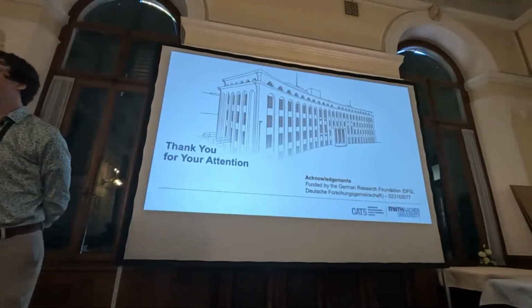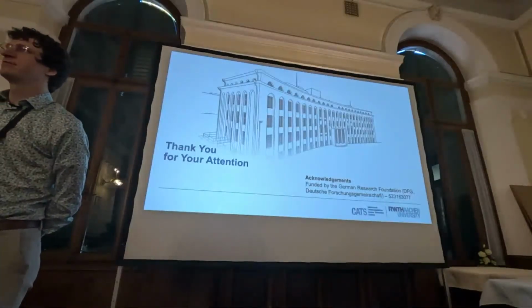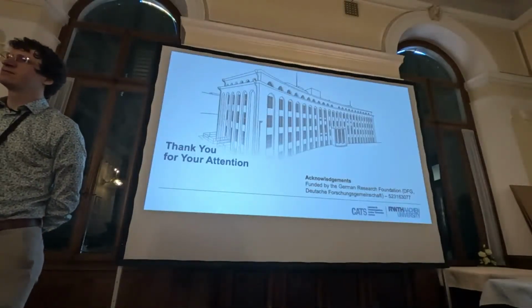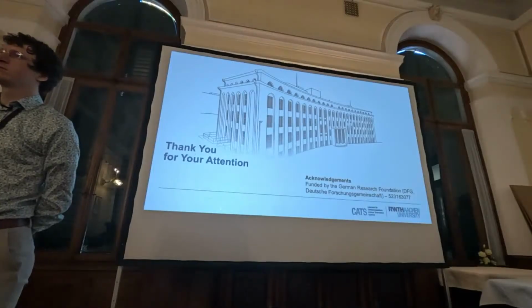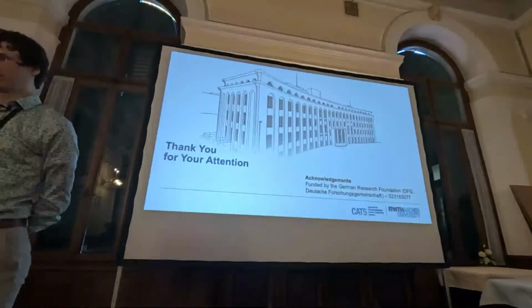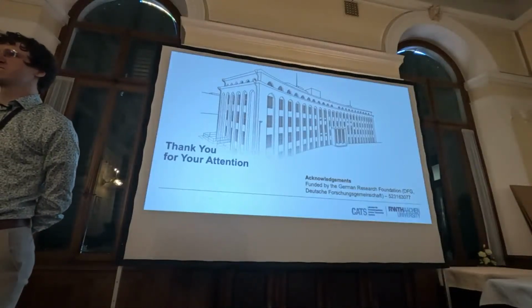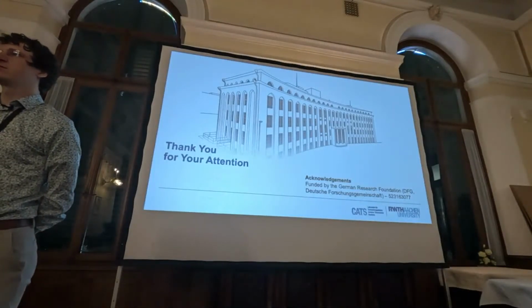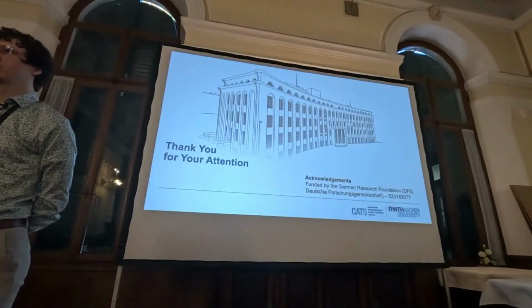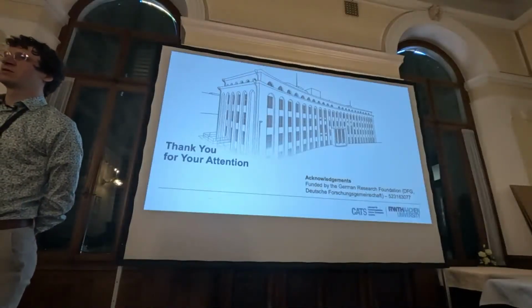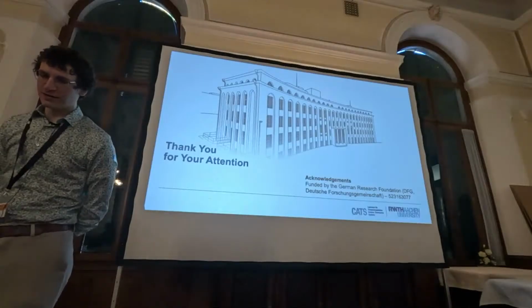Yes, please. Thanks for your presentation. Usually when it comes to applications, people solve the Reynolds equation, the first version of the Navier-Stokes equation, where you neglect the inertial terms, and then you use a solver, because of the problem complexity. And sometimes, when you have roughness, you even need to homogenize them. Have you a comment about your approach, or why you think that it is better in this case?